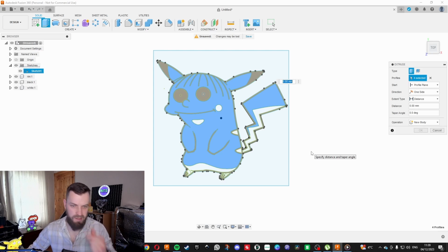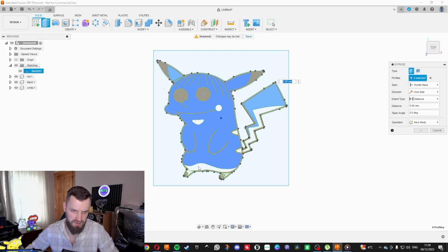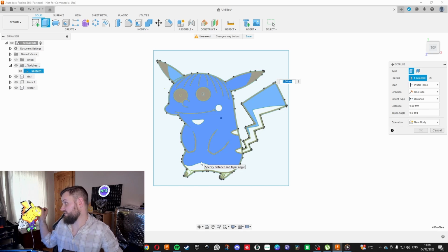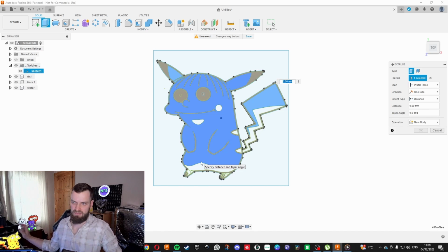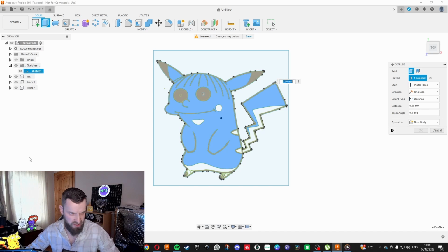And I'm gonna try to mix yellow and red in layers to create kind of a brownish orangey color. We'll see how it turns out at the end. But as you can see, I already did it and it looks pretty good, so it works. So you can actually shade your colors using only a 4 color AMS system like I do. Makes it yeah, more possibilities. Mix colors, create different shades.